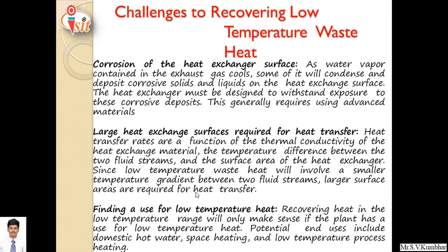And the last point is the challenges in recovering low temperature heat. The first challenge is related to corrosion of the heat exchanger surface. While extracting heat from low temperature sources, as water vapor contained in the exhaust gas cools, some of it will condense and deposit corrosive solids and liquids on the heat exchanger surface. The heat exchanger must be designed to withstand exposure to these corrosive deposits. This generally requires advanced materials.